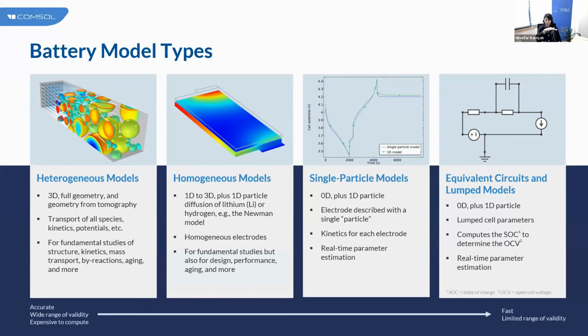All of these frameworks are well-established within the battery community, and they are behind the scenes of the physics interfaces in COMSOL. They have already been defined and embedded behind the physics interfaces. So two things I want to mention: these frameworks are already defined, and the second thing, which goes hand in hand with the multi-scale discussion, is that you see that complexity range, and it's your decision. Would you like to resolve all the physical phenomena happening inside your cell?